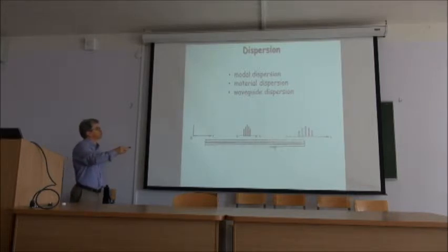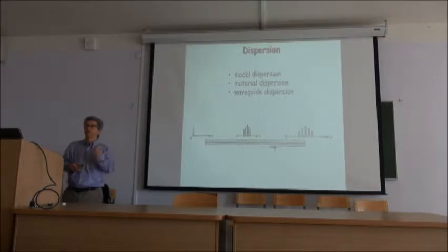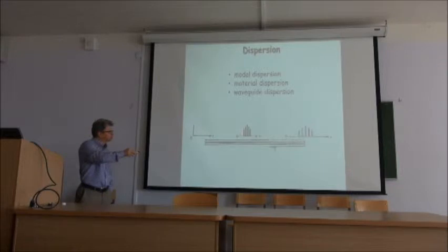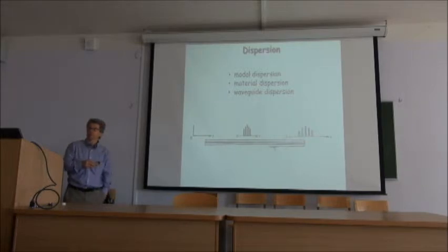But even in those cases there are other dispersions, and another one is material dispersion. We know that for any material, as I change the wavelength, the refractive index may change, so that can create a dispersion. So that's something that starts spreading those pieces of data that are encoded on the optical fiber, and that's problematic as well.